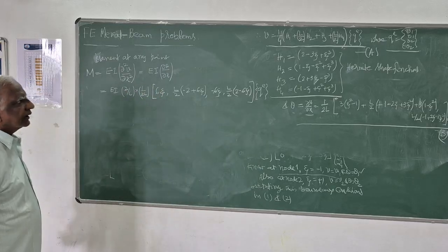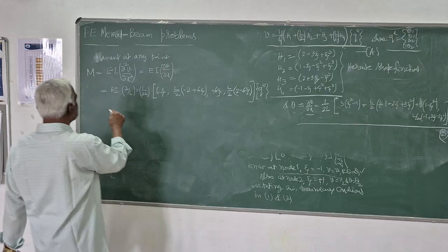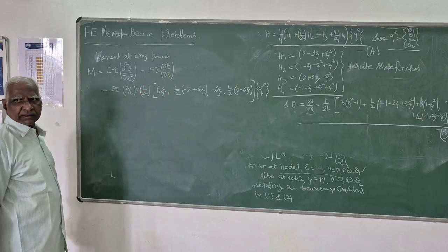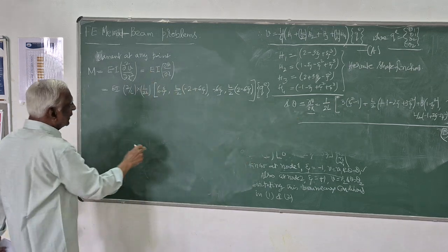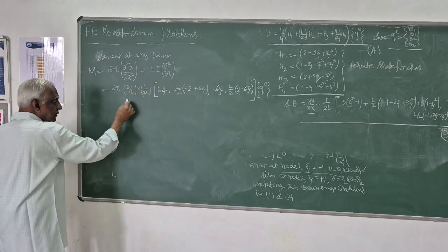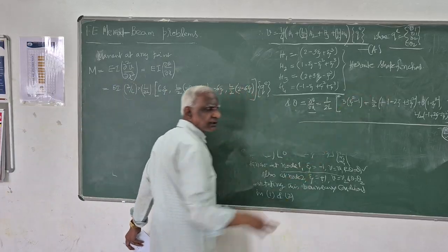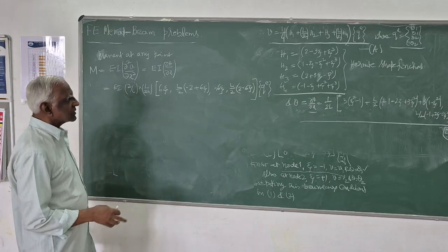And of course, the element nodal degree of freedom. So this is partially differentiated with respect to x. When we are differentiating this partially with respect to x, then I have to use the Jacobian inverse into the partial differential coefficient with respect to z. We can do that with respect to z.